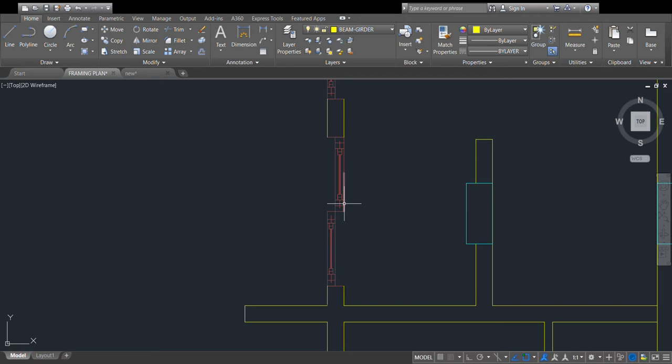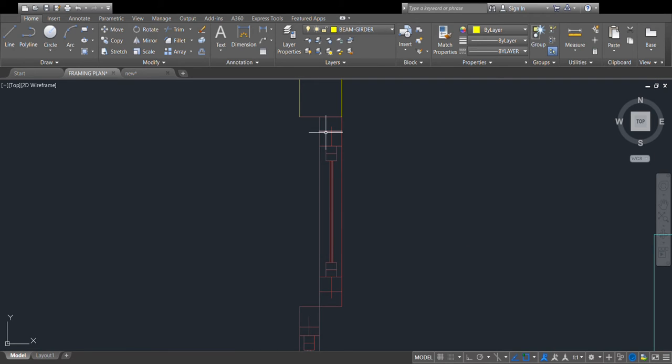Why? Because number one, the thickness of your window in total is not matching the thickness of your wall. So what do I mean? For example, SC, I'm going to say this portion only. Okay. Now I selected only half of the window. So press SC. Object, press enter. I will select this middle portion.